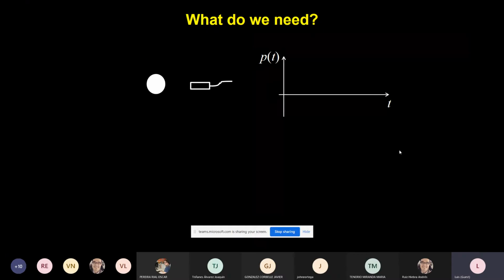So this is a small animation. A laser heats up the tissue and then generates an ultrasound wave, and we have a signal like that. This signal is very similar to what we get in ultrasound. For example, it is a time-resolved signal, a pressure signal. In ultrasound, they call it the RF signal or A-mode signal, or there are different names, but it's basically pressure as a function of time. It's an ultrasound wave that you detect.